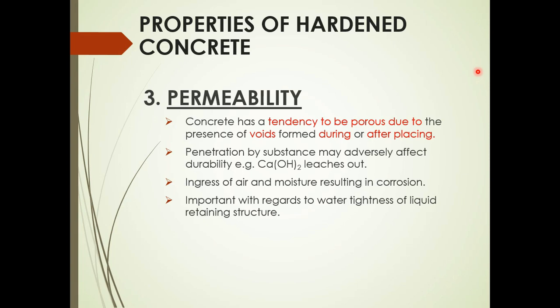Okay, the third property of hardened concrete is the permeability of the concrete. Concrete has a tendency to be porous due to the presence of voids formed during or after placing. The voids will cause the penetration of substances and will affect the durability of the concrete. For example, calcium hydroxide leaches out, and also ingress of air and moisture from the environment will result in corrosion of reinforcement in the concrete.